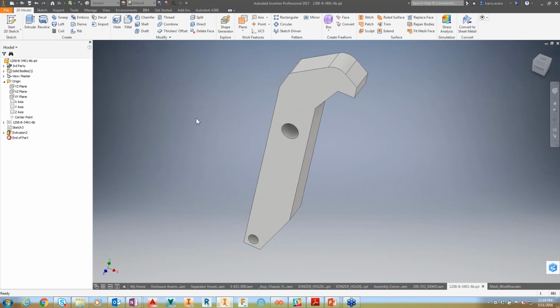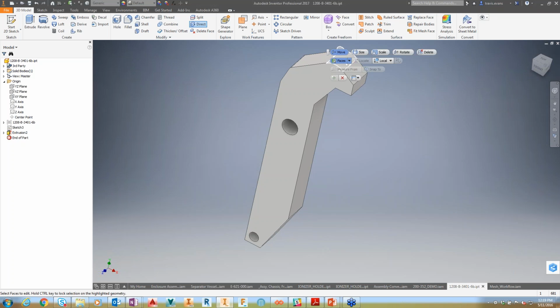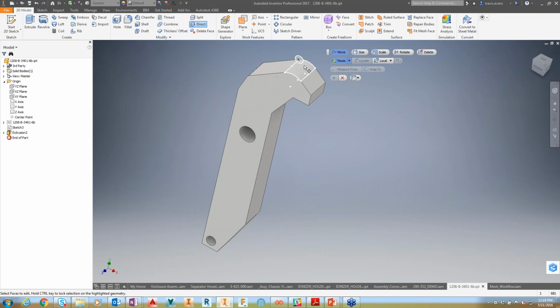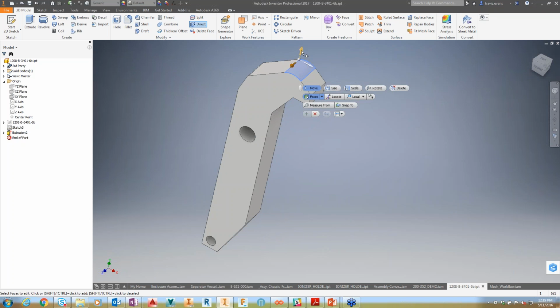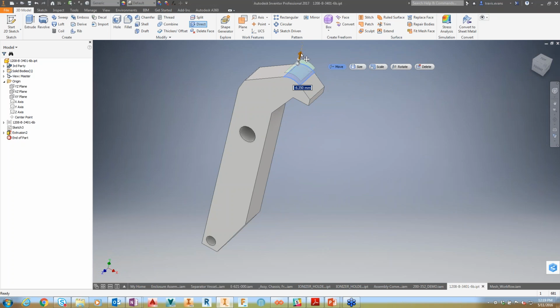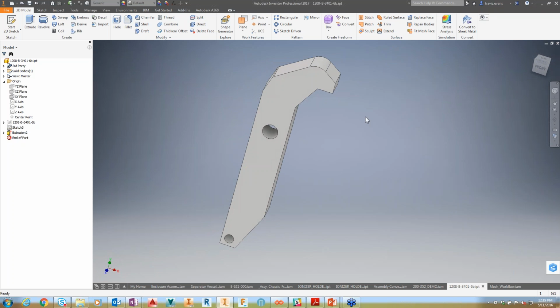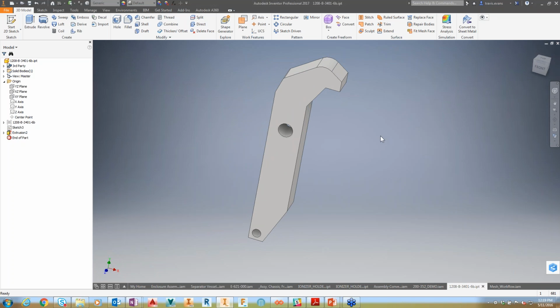As you start to think of ideas for this type of workflow, okay, now I can use that STL data to give me a starting point inside of Inventor, because now I can maybe modify this data and use some feature recognition tools, right? If I wanted to do some direct edits, well, now I have this top face, and I can push and pull and start to understand what's going on. I can modify that data, all starting from that reference point, giving me the capability to modify or manipulate data that didn't start as a native CAD file. It started as an STL or a mesh.